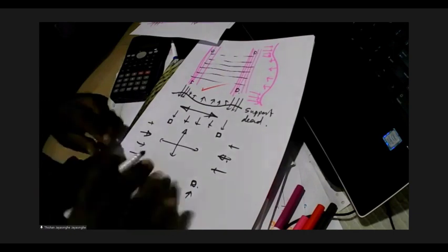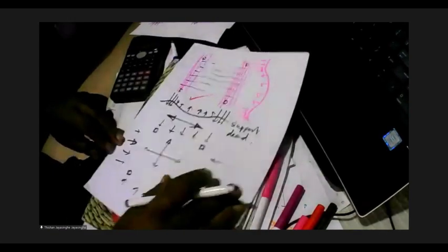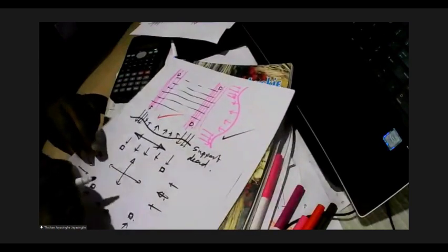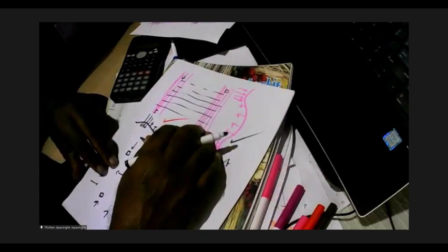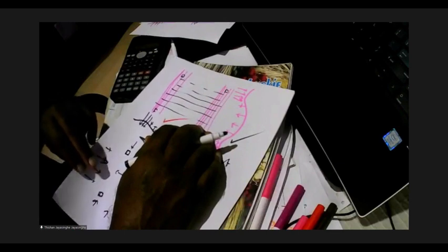So basically, we can have this two-way system or one-way system. And what we prefer is this one-way system these days. So first we compensate for the dead weight of the structure, and then we see the live loads and see whether the live load stresses are okay or not.